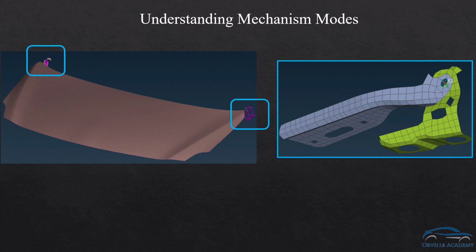The scope of this video is not to understand the modeling, but to see the modes coming because of the hinge connection. For the time being, imagine that with the hinge connection, the hood assembly is allowed to rotate. So essentially, we are releasing the rotation degree of freedom of the hood assembly. So, in addition to the 6 rigid modes, we should get another 0 frequency mode corresponding to the hinge mechanism. The modes which correspond to some mechanism are typically known as mechanism modes. Now enough with the theoretical discussion, let's do the exercise practically.